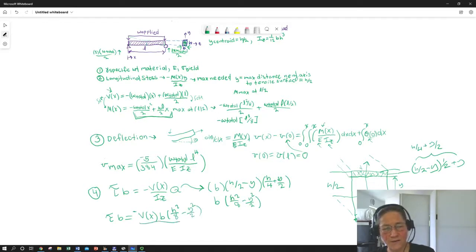And we're going to write out the expression for our moment of inertia, our 1/12 b h to the third, because unlike some cross-sectional cases, these two b's cancel, but we've still got a b in the denominator. So in this case, unlike where we had over here, we still had some dependence for our longitudinal stress on b. Then it was rolled into our moment of inertia.